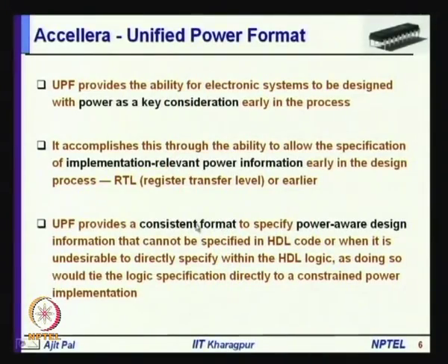So, UPF provides a consistent format to specify power aware design information, which cannot be specified by HDL code. As I have told, HDL has serious limitations, and it cannot really incorporate most of the low power features that I have discussed, or it can be used when it is undesirable to directly specify within the HDL logic, as doing so would tie the logic specification directly to a constant power implementation. So, in both these cases the power intent will be specified with the help of UPF.